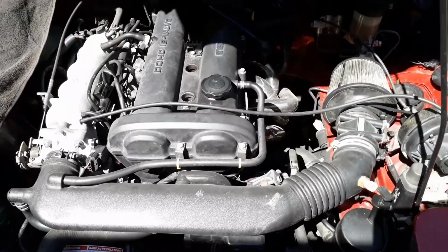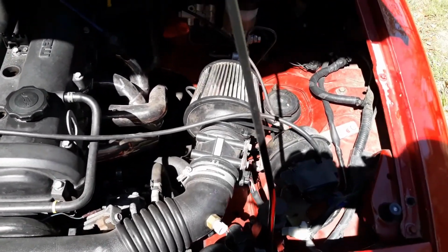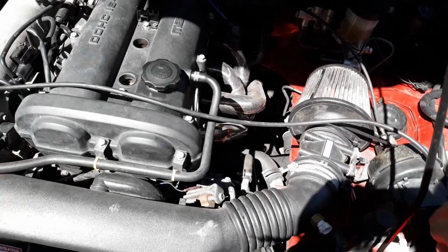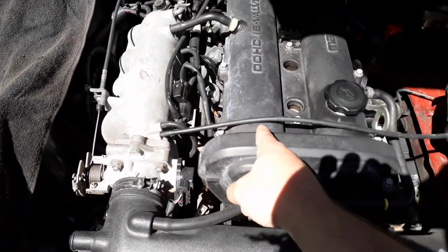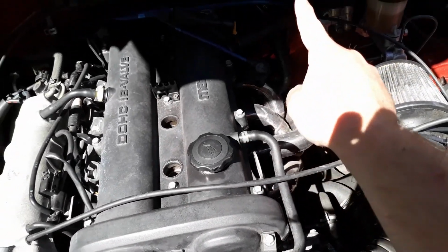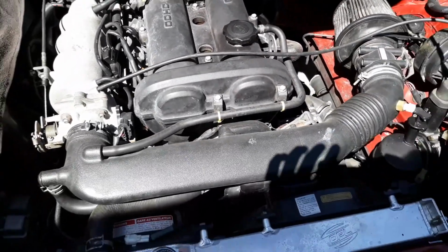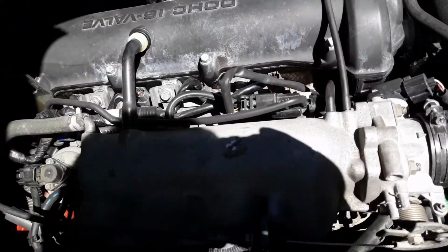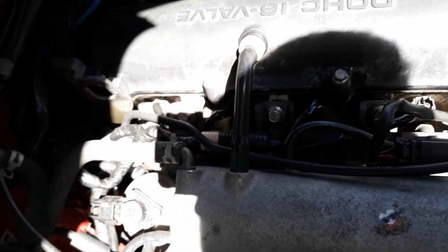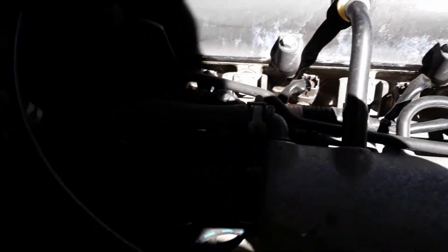Anyway, so here we've got this Miata. So air, it's always going to have air. Even if you disconnected the intake, it'd still get air through the throttle body, so it's never air. So we're looking for why this engine doesn't run. There's the injector rail, but I always start with spark. Spark is the easiest to prove.